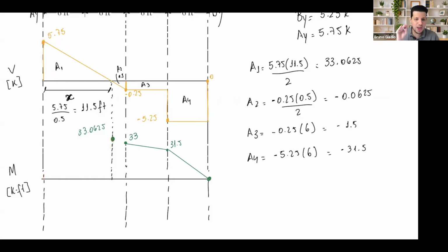For those, take a look where we have shear 0. Shear 0 is right here. Shear 0 means the slope at this point should be 0. What is the slope 0? It's kind of a straight line here. So what is the curve that goes like that, this curve or that curve? The second one. So this is how it's going to be. This is my moment diagram.